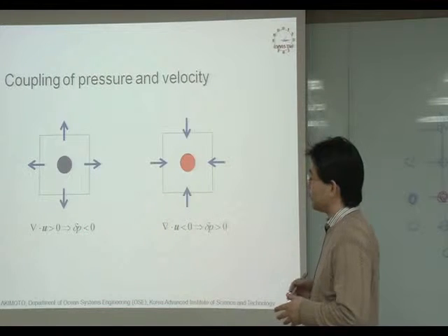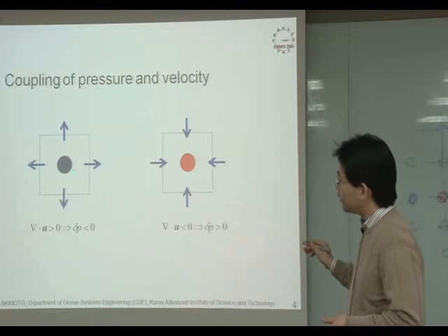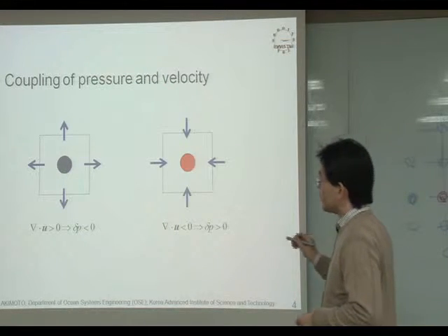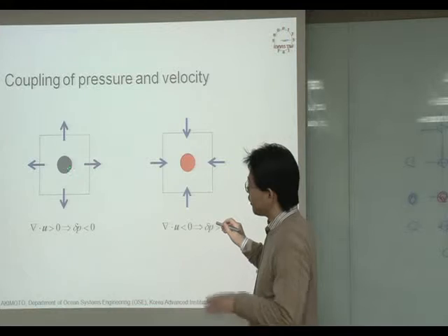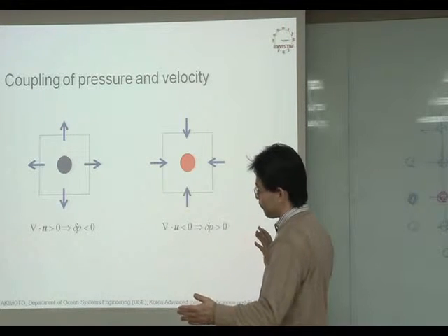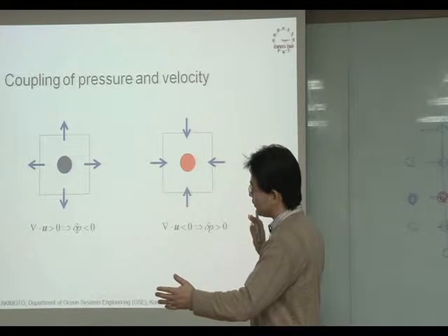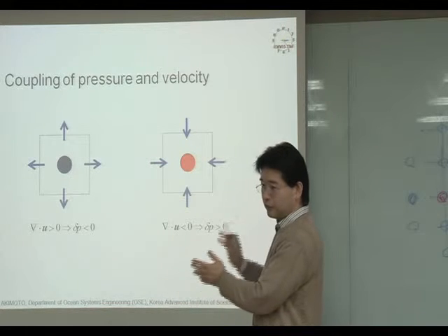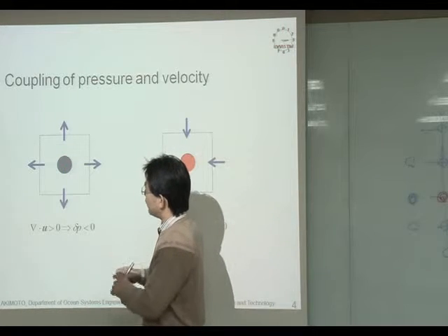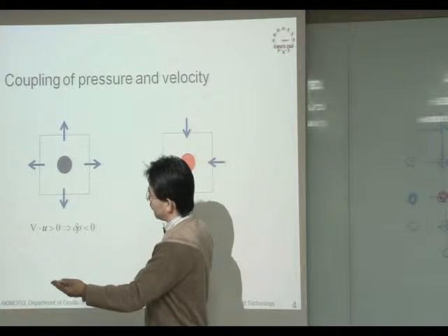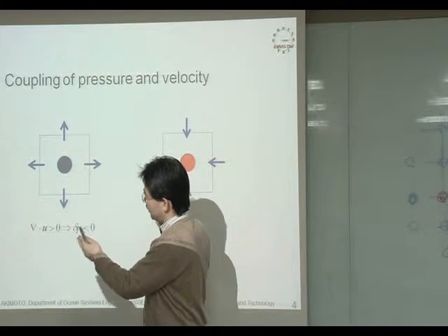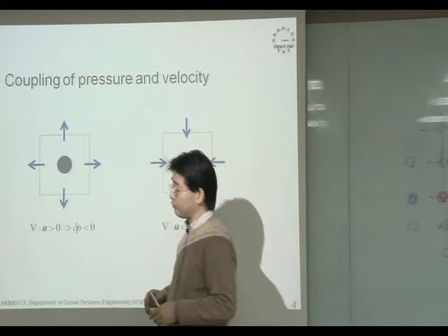Change of pressure should be negative. In the iteration of pressure solution, the next pressure should be slightly decreased to attract the escaping fluid. By decreasing pressure, it will attract escaping flow into the center of control volume again.